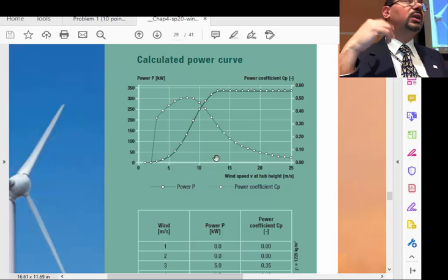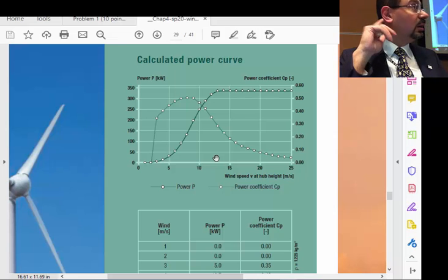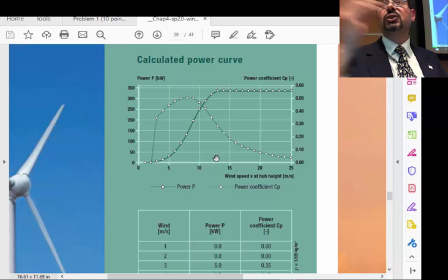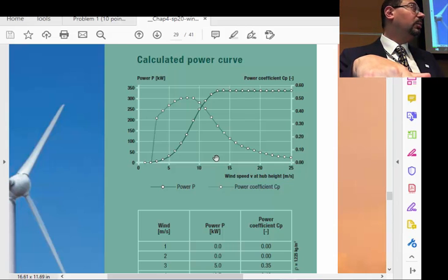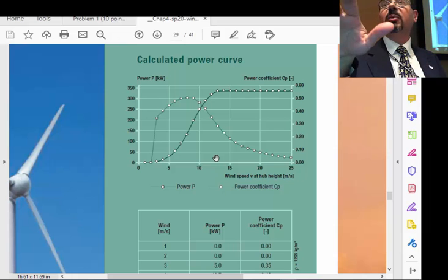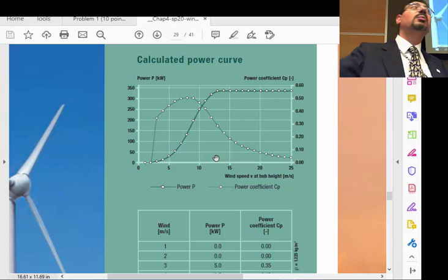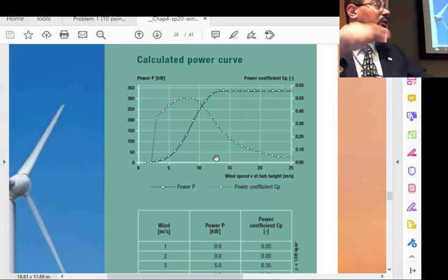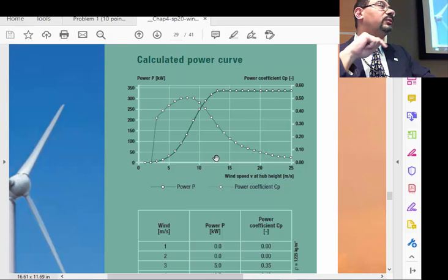Okay? So each kilowatt hour, how much do we pay roughly in Oklahoma? 11 cents. That's a good number. So for every kilowatt hour, we pay 11 cents. If you are the company that's running this one, whatever megawatt hour you have, you multiply this by 1,000 so that you get the kilowatt hour, and then multiply by 11 cents, and that's how much money you are generating from that turbine. Okay? I'm asking, how many years does it take to pay back the turbine? You will get it from that calculation.